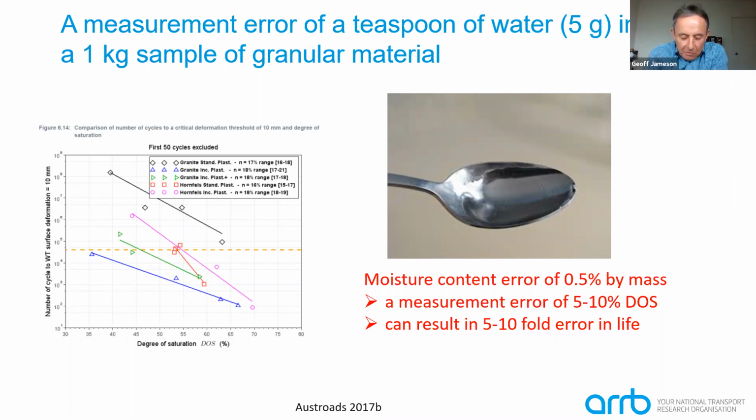We haven't done a lot of work in terms of pore pressures and the influence that you're talking about, but I think I've demonstrated through the series of slides here the significance of that. When we measure the characteristics, both the modulus values of subgrades and of granular materials, the variation with moisture content affects modulus values significantly, and also the deformation characteristics.